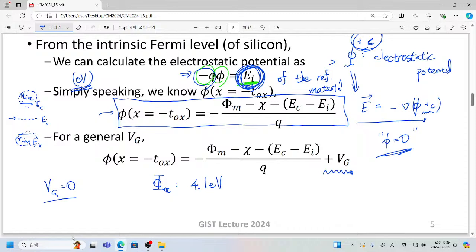If you are working with a P MOSFET, usually you want to use a much higher value, close to 5 eV. This one is quite widely distributed depending on your device, but for now let's just say this is the typical number.